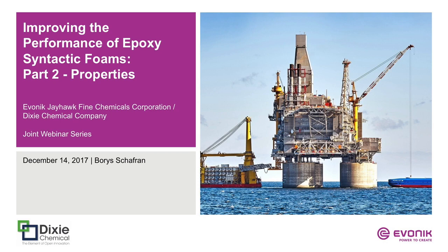In today's presentation, as we also touched upon in Part 1 of our webinar series, our focus is on the deep water exploration of oil and gas reserves. And in this type of application, where ocean depths are greater, where longer lengths of rigid pipe are required, the reliance upon syntactic foam as an insulating layer for these pipes to ensure the transport efficiency of the crude to the surface becomes more vitally important.